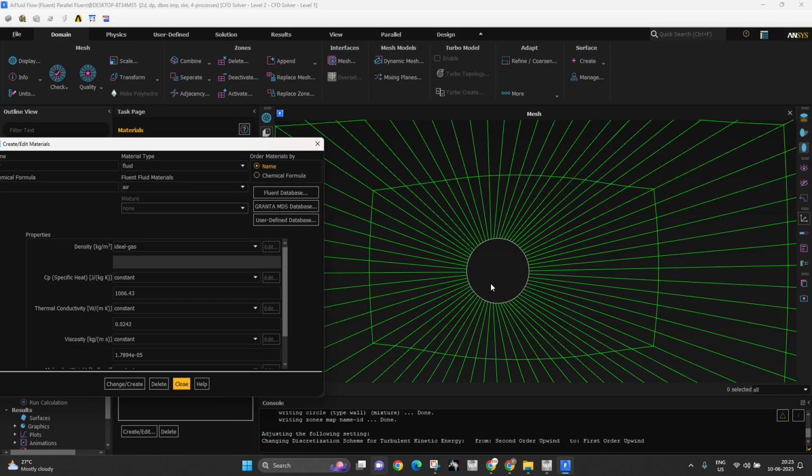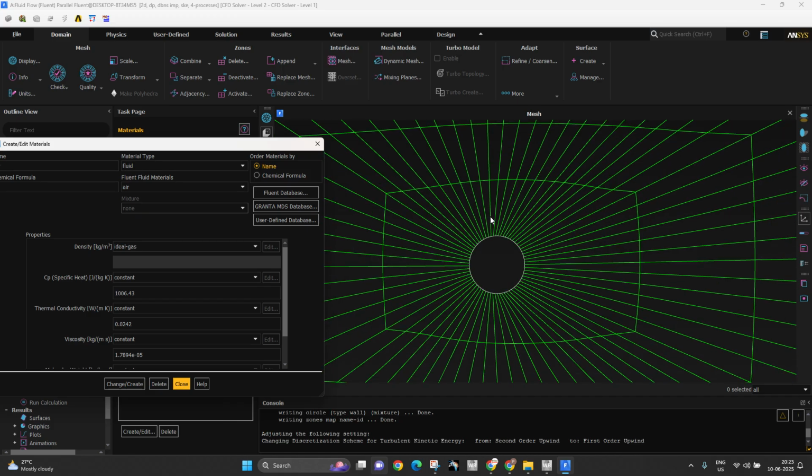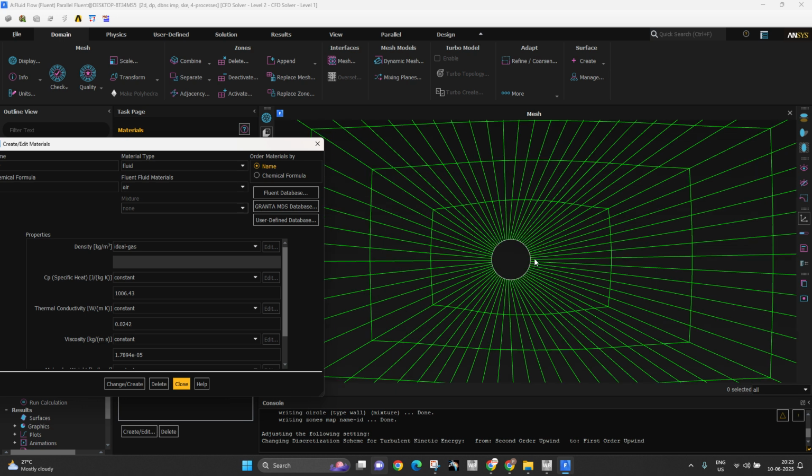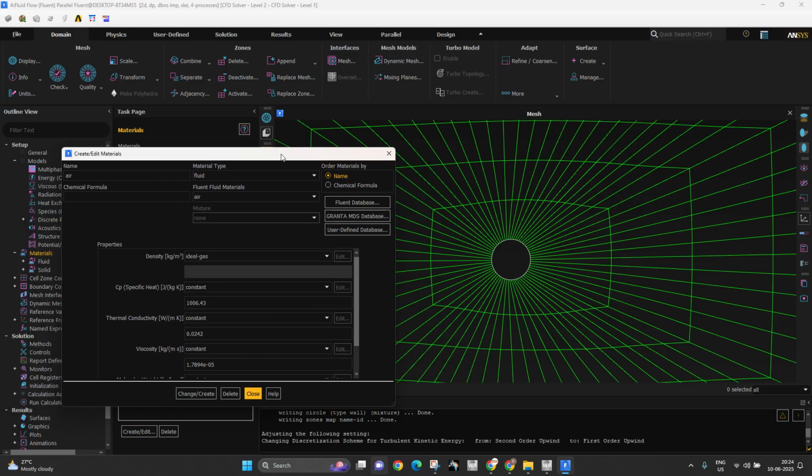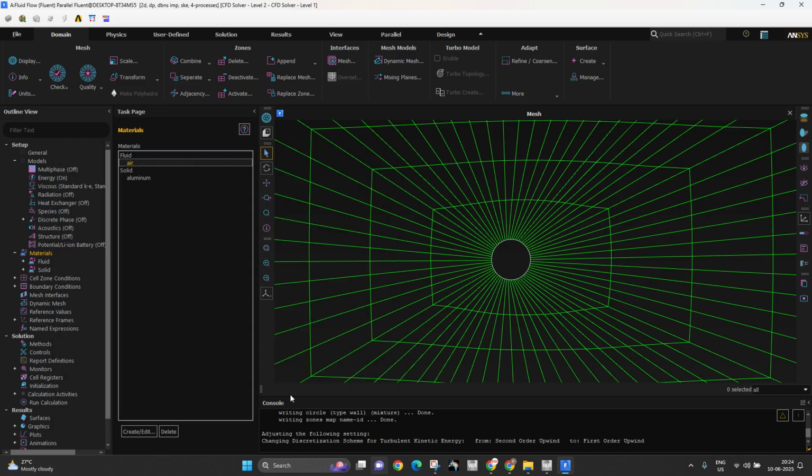The reason I make sure there is ideal gas flowing over a circle is because I should get to know what happens with sudden temperature and pressure changes. This might alter the velocity effect, right? So to make sure everything is in line, if I choose ideal gas, it obeys all the different types of gas laws, right? This will autonomously adapt itself to any sudden changes. So click on create and close it. You're just naming the environment, that's it.